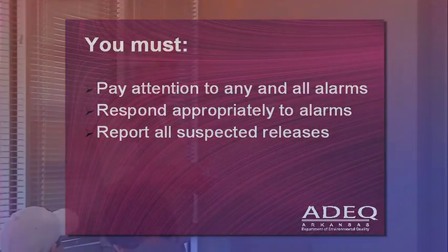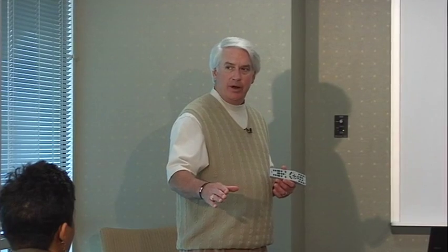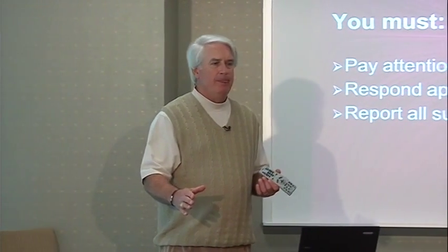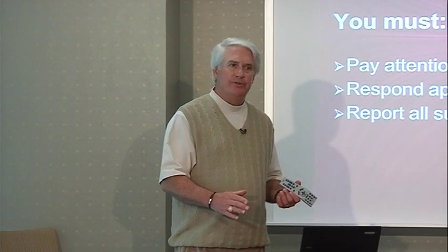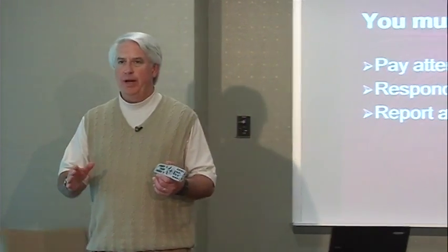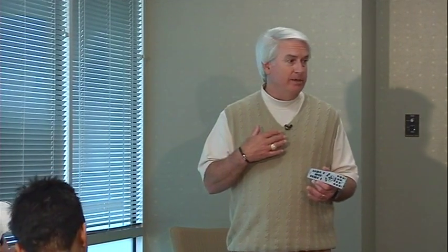You have to respond appropriately to the alarms, and then you've got to report all suspected releases to ADEQ within 24 hours. That's really important if you want to use the Petroleum Storage Tank Trust Fund. Anytime that you have a suspected release, you need to call us. And let me point out too, that if you have a release or a spill at your facility, that's not a violation. The violation is what you do in the next 24 hours, and in that next 24 hours, we've got to be notified.